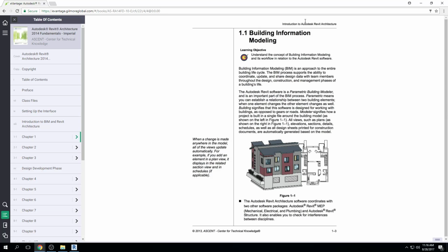So I'm taking this one model, and in order to look at these different drawings, I'm viewing it in a different fashion, right? Does that kind of make sense to everybody so far? Okay, so I look at the floor plan, I look at the elevation, and you're probably thinking, well, what about these sheets, okay? Well, the sheets are also contained in here. So my drawing, my model, my views, and my sheets are all contained in this file. Okay, so we'll just do like A101, A201. They're all contained in one central file, okay?